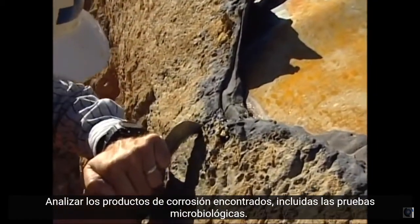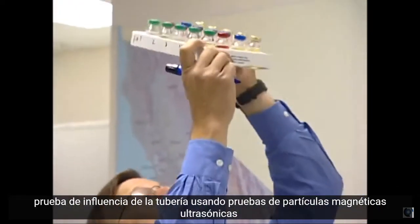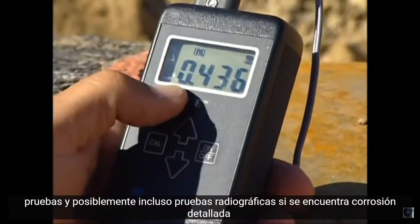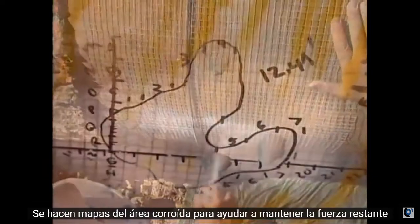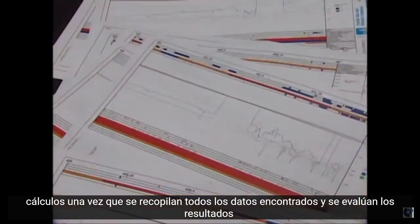analyzing any corrosion products found, including testing for microbiological influence, testing the pipe using magnetic particle testing, ultrasonic testing, and possibly even radiographic testing. If corrosion is found, detailed maps of the corroded area are made to assist in remaining strength calculations.